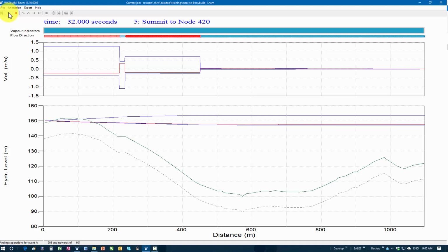We are seeing the benefit of using stored energy in the pressure vessel as a way of directly addressing the power failure problem. As a solution, the pressure vessel is far more effective in terms of controlling transient heads, and its benefits are experienced across the entire pipe network.